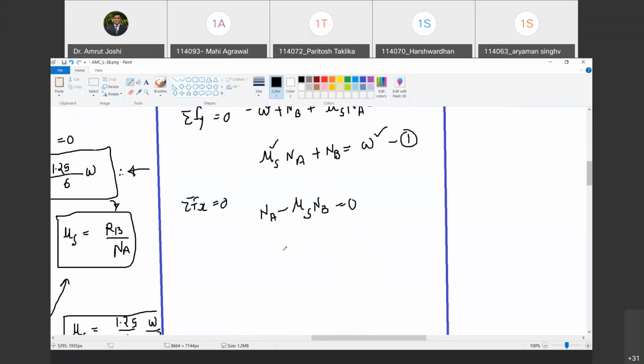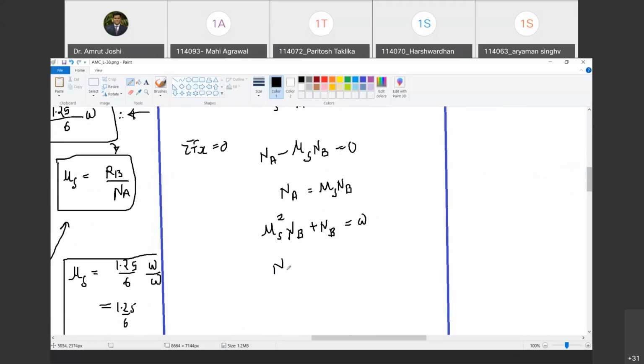Yes, sir. So how much is Na? Na is equal to µs times Nb. Substitute that in equation number 1. So what do I get? µs times (µs squared Nb plus Nb) is equal to W. Happy? Yes, sir. So how much is Nb? Tell me. Nb is W upon µs times (1 plus µs squared). This is the value of Nb.